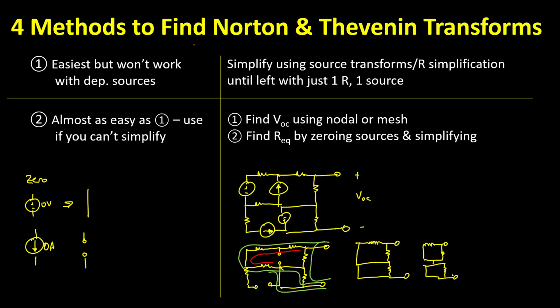I think it's pretty clear that I haven't changed the nodes that any of these resistors are drawn on. All I've done is split this line into two lines. And now it should be clear that these two resistors up here are in parallel, because they're combined at the top and the bottom. So these guys are in parallel. These are also in parallel.